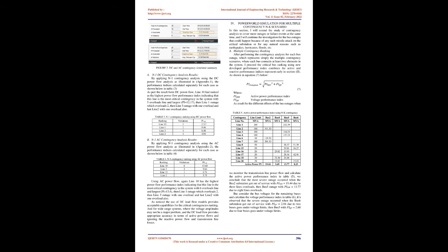For real-time security analysis, the impacts of hundreds or even thousands of outages on line flows and bus voltages must be examined. This depicts the real need for the speed, accuracy, and acceptance of the solution technique. In reality, solving with full AC power flow is not feasible for all contingency scenarios, because a large number of these contingencies do not result in severe generation shifts or transmission line violations. The objective is to eliminate the major part of harmless scenarios from the short list of branch contingencies.